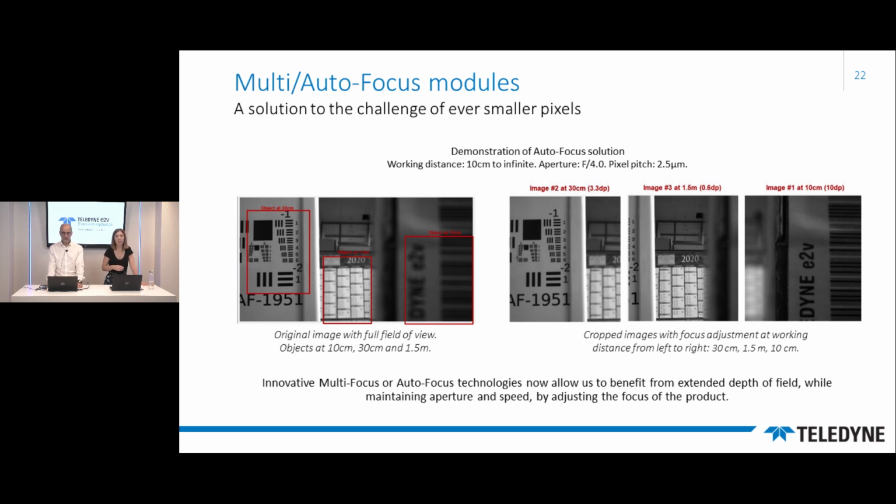And so as we noticed from the graph on the previous slide, we cannot have everything in focus with that typical scenario, knowing that, as mentioned on the bottom, in this typical case, for instance, pixel pitch I took 2.5 micron, which enables my solution, for instance, to fit with M12 mount, so cost-effective and compact lenses. And I took an f/4 aperture, which is quite open. At least can be more open than what we use typically for decoding barcode usually. So quite larger aperture to be able to still get light sensitivity.